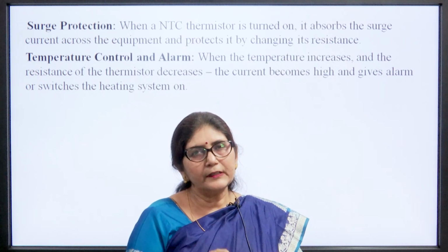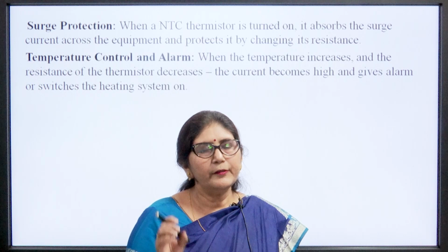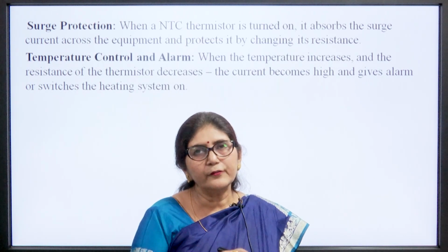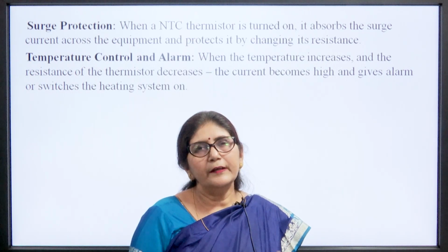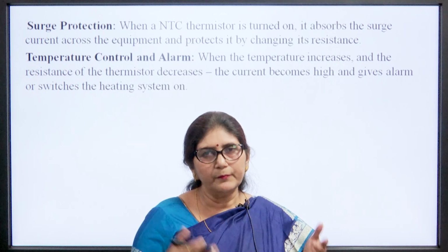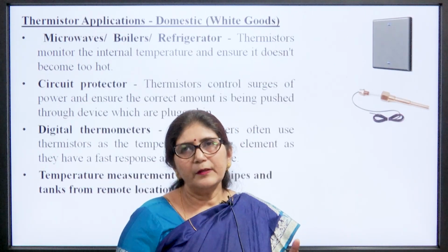So, if the temperature decreases in a microwave oven or any other place, we will get an alarm that the temperature is decreasing, because the resistance is high and so low current will flow through it. And when it gives the alarm, the temperature can be increased. So, these are the thermistor applications.